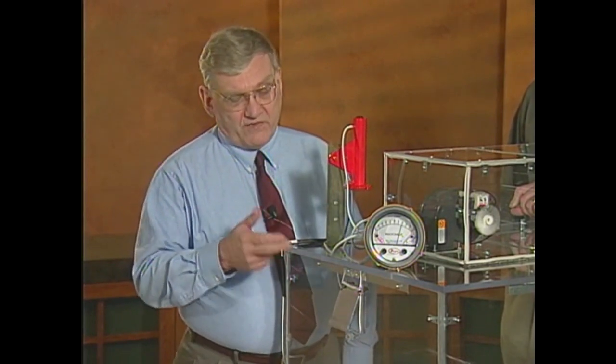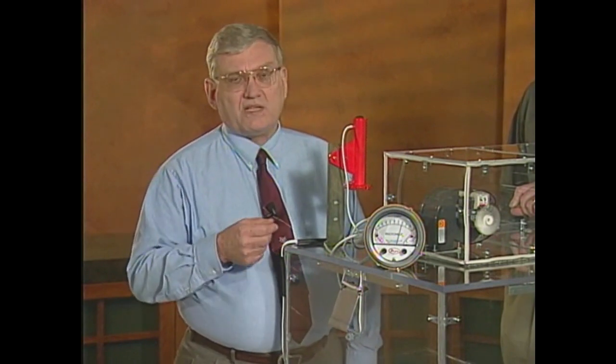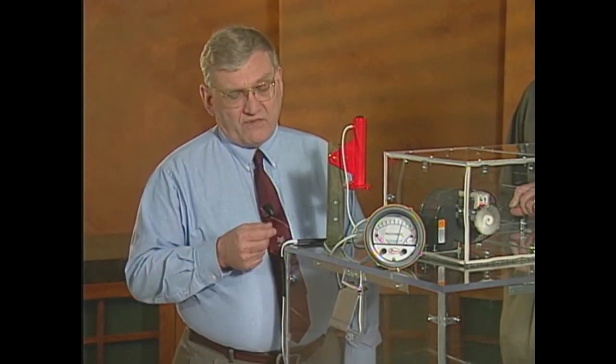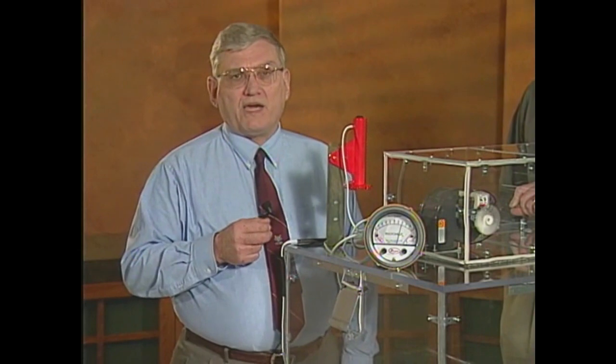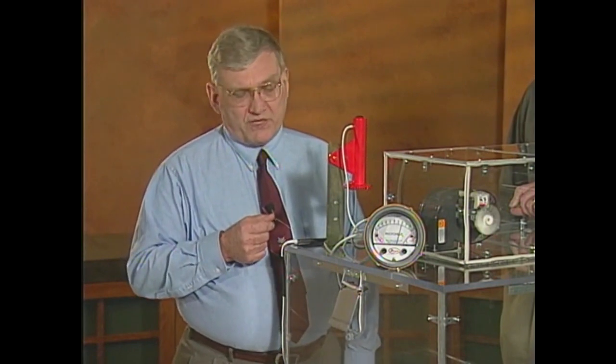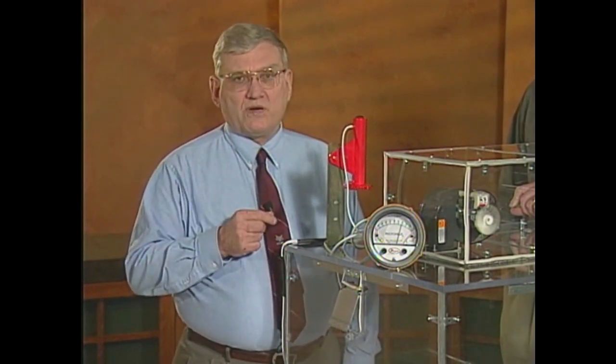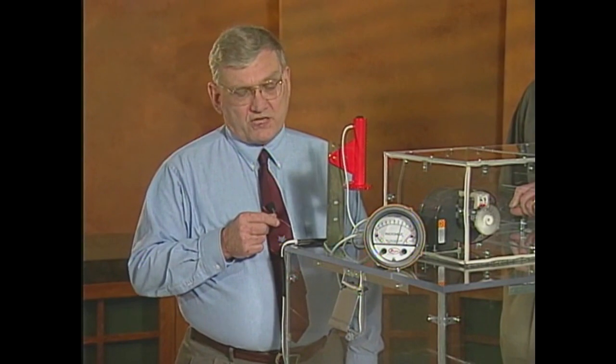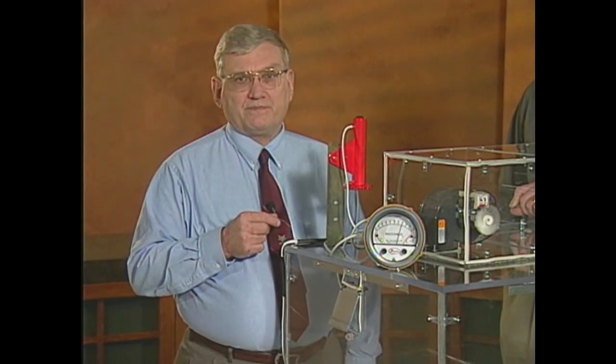Barometric seals are very important. Remember, you have a hole in the building. You want to prevent infiltration back into the building when the damper is closed. Consider insulating the barometric damper. And then finally, you'll probably want to put a bird screen behind it to make sure that no birds end up in the building. Local barometric damper sizing is important. Typically, they're sized for full CFM exhaust at 0.2 of an inch static pressure. Dennis, what's next?